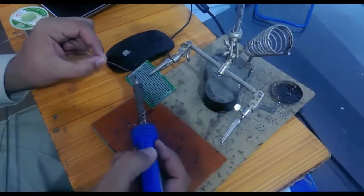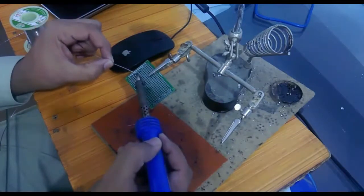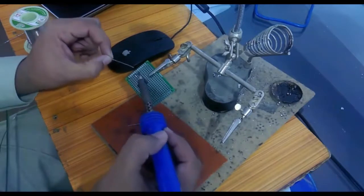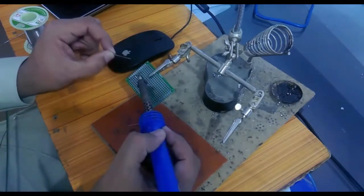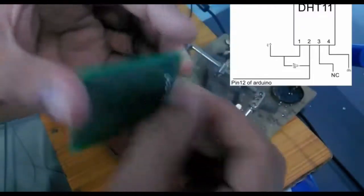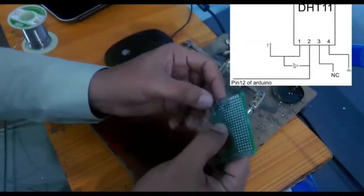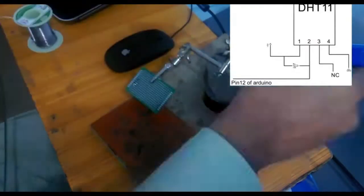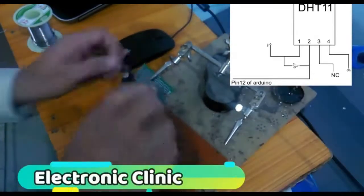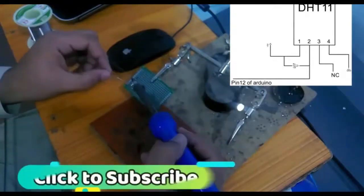While soldering, make sure that you don't apply too much heat, because this can damage the DHT11 sensor. Now as you can see there is no short circuit, and we are doing all this soldering as per the circuit diagram. Now it's time to solder the 10k resistor as per the schematic. Now the 10k resistor is soldered.